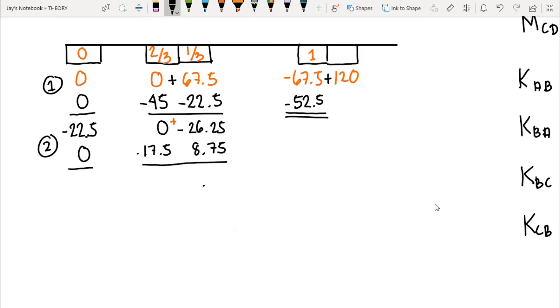So we carry over the moment, then divide it by 2. So we have 17.5 divided by 2. So we have here 8.75, but we still have here 0. But since we do not have a moment that can be carried over to the right side of point B, that means we can stop at this point. So we have a 0.